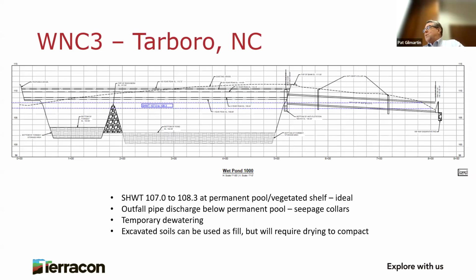But another war story here: most of the outfall pipes that I've seen problems with do have relatively steep slopes and steep gradients. The ones that have blown out, I saw one in Charlotte years ago, and it was like, wow, I can't believe they put that thing in. So I don't think they're going to have any seepage problems on this site, but a couple of seepage collars aren't that big a deal.